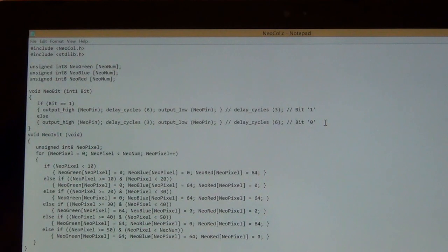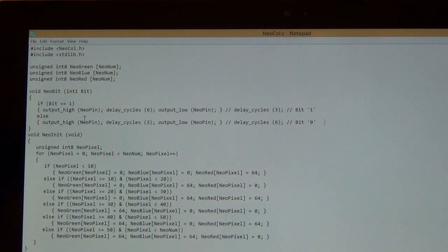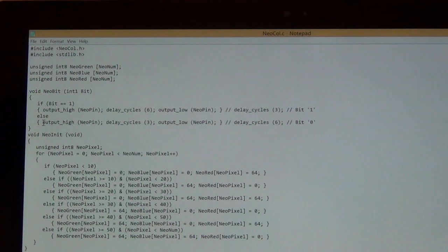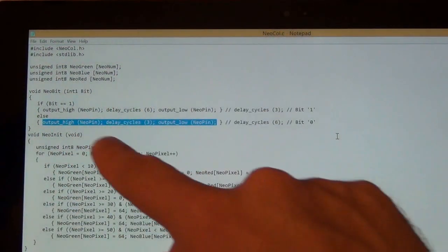So what I'm doing right now on the development board is constantly writing the bit 0. That's all. Forget about the rest of this. All my code is doing right now, programmed into the microcontroller, is constantly setting the bit 0 and nothing else. I want to make sure that waveform actually matches this waveform, which means the compiler only executes these 3 commands in a row before coming back and doing it again. So it's just going in a loop over and over, running this.